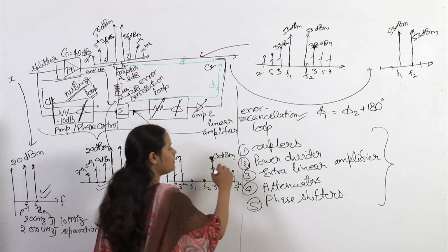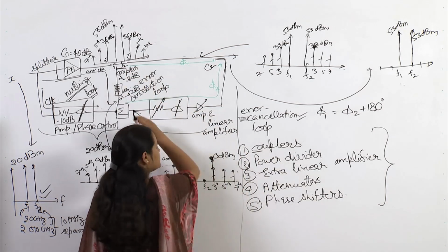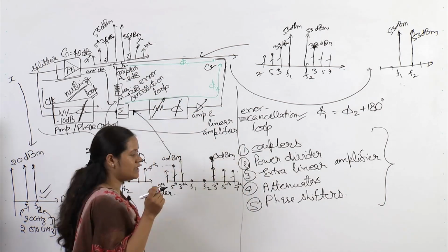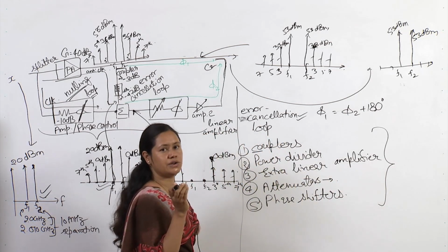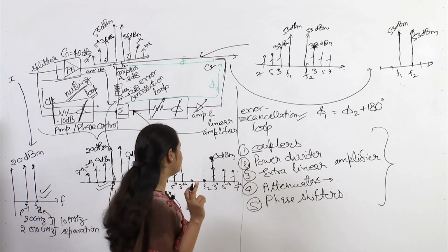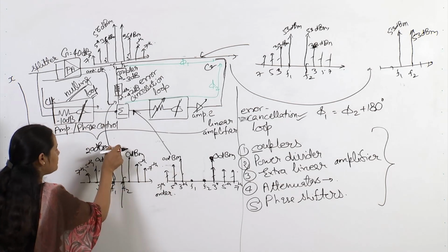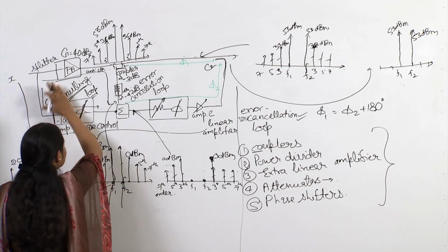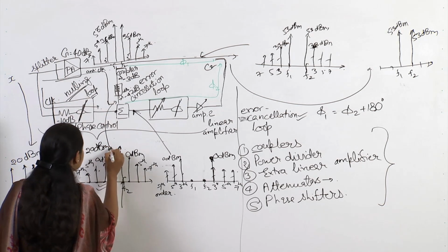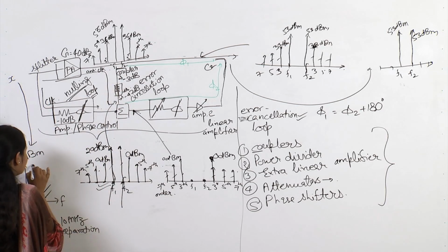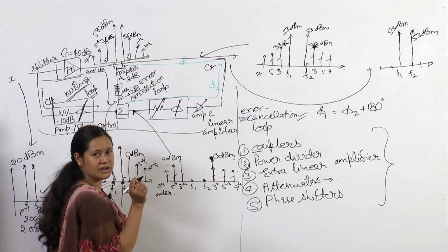So, each of them introduce their own errors. For example, this coupler will have some losses there, those losses have to be calibrated properly. These attenuators have to work in a very fine tuned way. Why is that? Because in both of the loops you had seen that there is utmost importance that the power level should match. For example, in the first nulling loop, if your powers are not matching for your P output and the signal output, then this tone signal will not be completely cancelled.